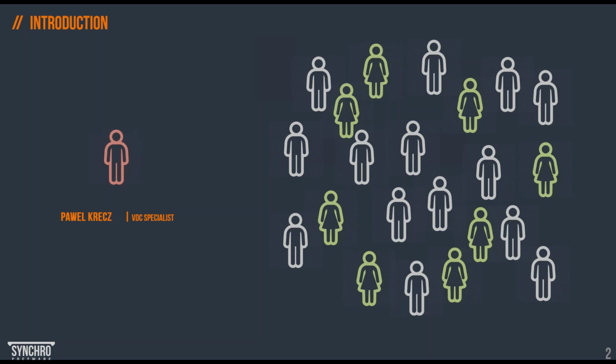SYNCHRO works as a completely independent planning software. With SYNCHRO we can create and link tasks, build and assign resources, schedule and calculate the cost, save baselines or different scenarios of our schedules, and finally monitor and control our program, report any variances, report progress, and so on. Everything that planners usually do, SYNCHRO can cover; it can be an independent planning platform.